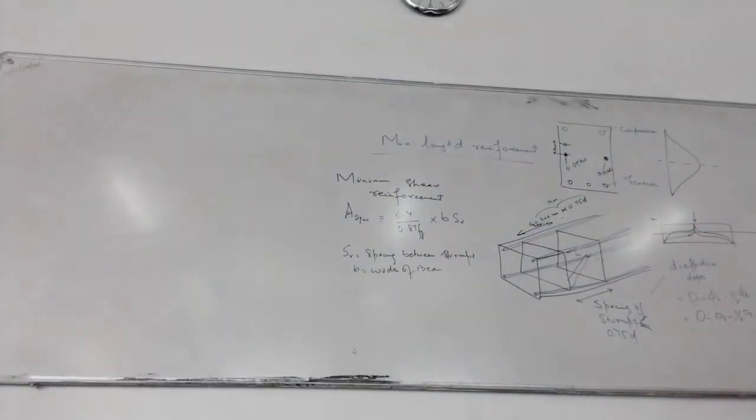Where the maximum shear stress calculated is less than half of the permissible value and in members of minor structural importance such as lintels, this provision shall not be complied with. So lintels are also beams, but there we do not provide the shear reinforcement because they are not deep beams. Lintel beams are not provided as deep beams.